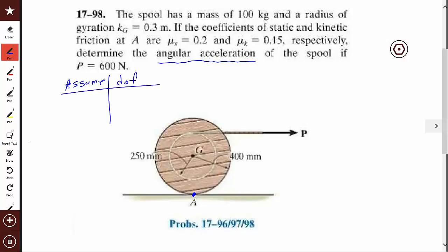So what could happen at A is it could slip. If it slips at A, the degrees of freedom is 2 because the wheel could rotate, and it could also slip. If you stop the rotation, that's 1 degree of freedom. If you stop the rotation and continue to pull, it could slip at A. That's what your assumption is. So if you stop it from slipping, stop it from rotating, then nothing will move, and so you stop counting, and it's 2 degrees of freedom.